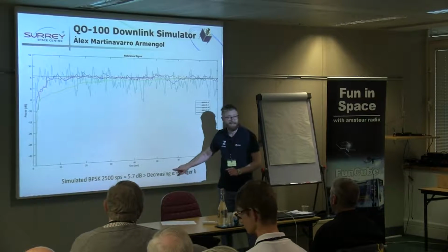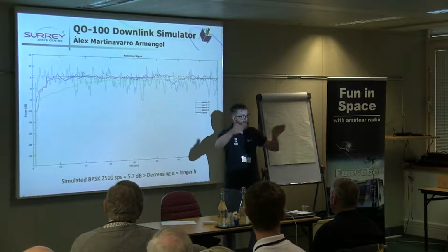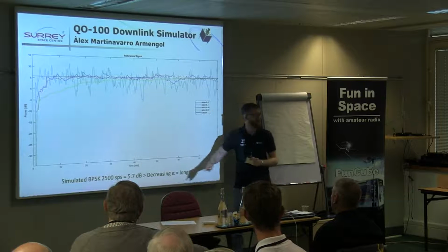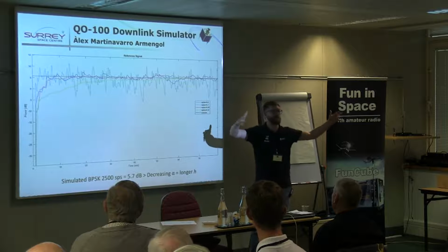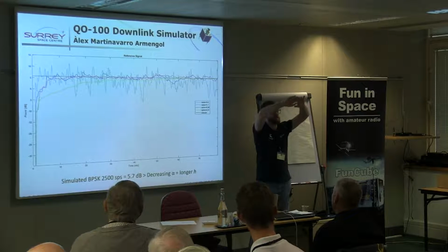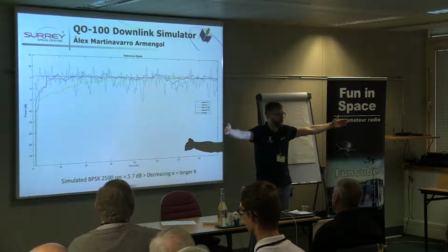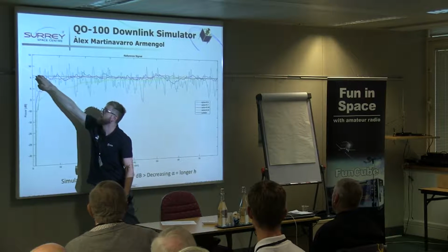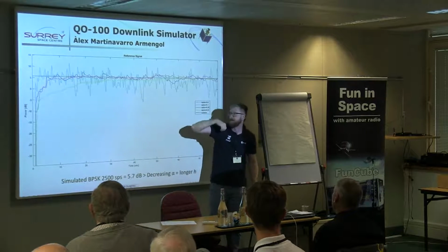But depending on really how you're measuring it and what power you're physically measuring across what bandwidth, which is directly related to your sample rate, you get different results. And so if you are actually using an alpha of 0.6, where this is something that is actually quite wide, this is essentially quite a harsh roll-off if you think about it from a filter point of view, then actually you end up having quite a lot of noise in. And does it actually fit the theory? Yeah, broadly, if you were to take the mean averages.